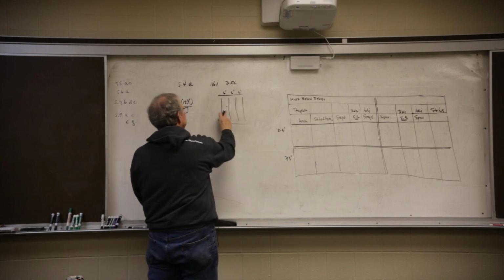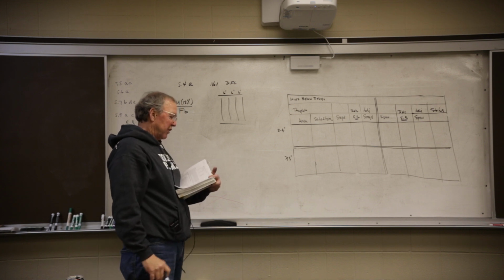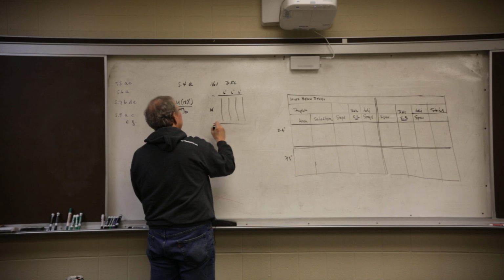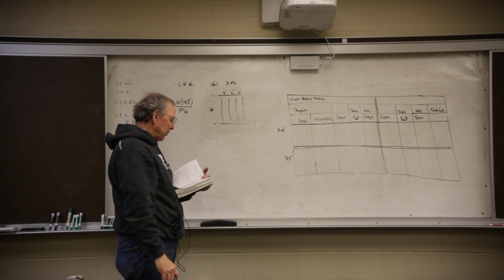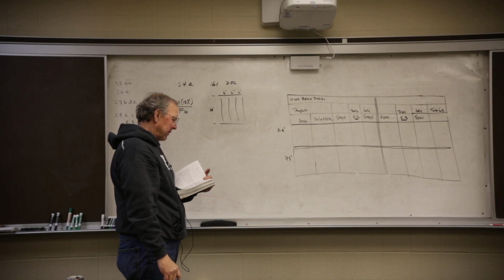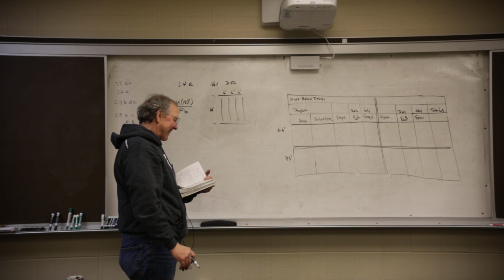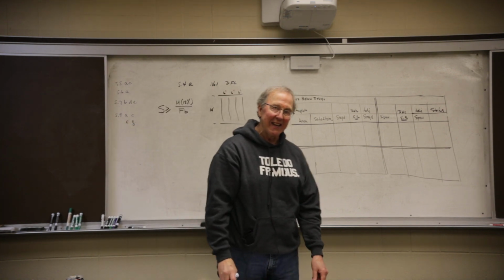There's the beam. These are the beams. Okay, 6 foot on center. They span 14 feet. Span 14 feet. If the total uniformly distributed load on each beam, including the weight of the beam, is 3,200 pounds, select the section with the least cross-sectional area based on bending.